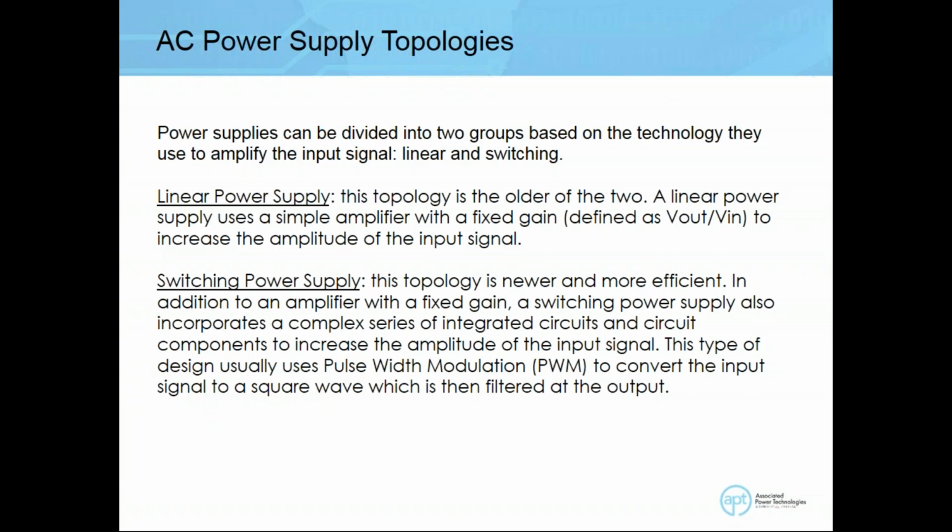Now these are bulky, in the sense that the transformer itself takes a lot of the weight. And it's really not that efficient because a lot of the energy loss goes into just powering up the transformer. The newer technology is known as a switch mode power supply. For switch mode power supplies, you have integrated circuits working in conjunction with other circuitry. The main purpose of a switch mode power supply is that it generates less heat, is much lighter, and is able to do all this on a smaller footprint.